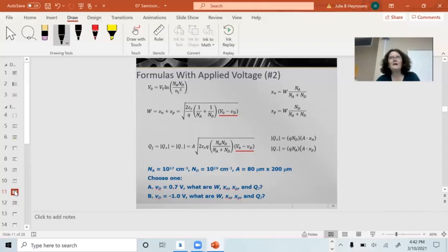Okay. Why are diodes so important? They show up in a couple of little circuits that you use. They're protection diodes, ESD protection diodes. They show up in power circuits and power conversion circuits. They're not really a big deal when you're talking about processors or logic until we get into studying MOSFETs. And there are diodes all over the place that you don't even see. A lot of the non-idealities of MOSFETs are based on the fact that there are all these p-n junctions in there. But they're actually pretty straightforward.